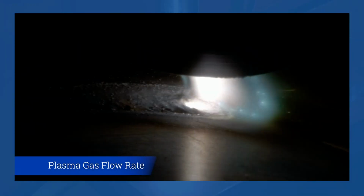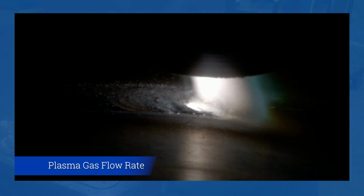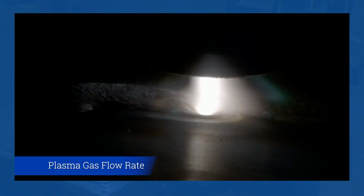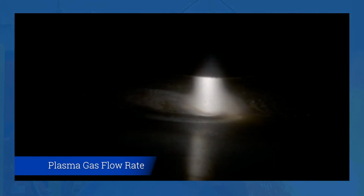Let's talk about plasma gas flow rate, a critical variable. Once you set it, you seldom adjust it. In this case, we're running 2 cubic feet per hour. It looks pretty good. And then let's turn it up. Now what you see here is we've actually made a divot. We've turned this into a cutting torch. If you were to analyze this part, it would have tremendous dilution and very low hardness.